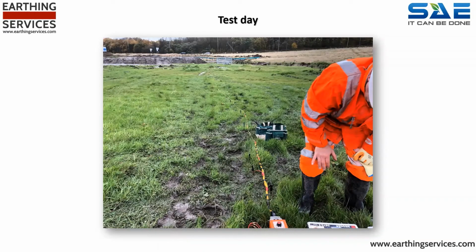When the engineers arrive at site, they may well have to be inducted, receive a briefing, or hold a meeting with the client's representatives. And all of the time, they will be evaluating how the activity on site, both current and historic, may have impacted upon the substrata. Prior to setting up the first soil resistivity survey location, it is common for Earthing Services engineers to visually inspect the area, including assessments on local flora and fauna. Mature trees or subsurface agricultural elements can distort or bias electrical resistance within the ground, and as such must be avoided, and reading the landscape is always informative.